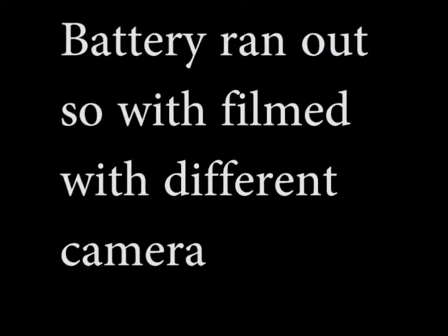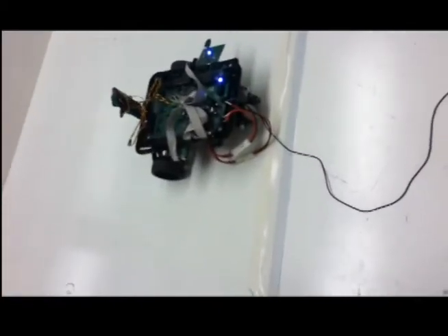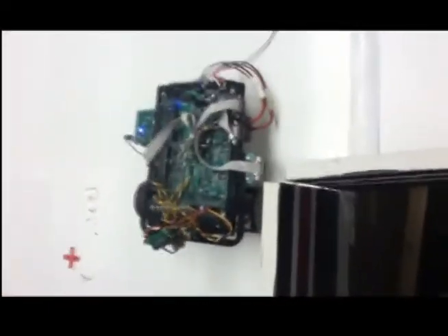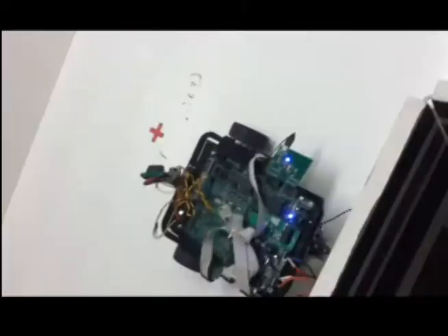Wavefront works by designating the goal value as 1, and it increases the values around it, then goes to the next point and increases the values around it, and continues on to the current location of the robot. That way the robot just takes a step into a square with a smaller value, and thus it has moved closer to the target. Wavefront was very effective and efficient in reaching the destinations of our waypoints.